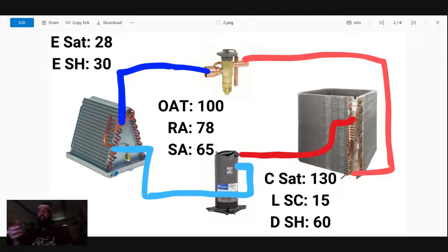Now we could test that. If you really thought, okay, I've got an oil log problem, a quick test for that, which you should be very careful with in the field, is you manually cycle your condenser fan, and you run your condenser head pressure higher artificially via the fan.